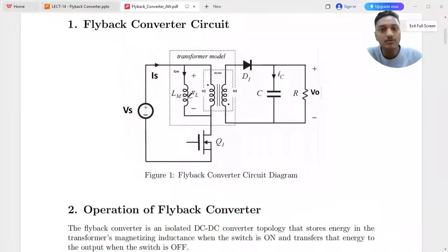Now, how this particular topology has come up, that part I am not going to cover. But what key observation should you have? You have this switch, which has a drain terminal, if I take the MOSFET, and this is my source terminal. I have seen that sometimes people use this switch here, but that is the wrong thing.